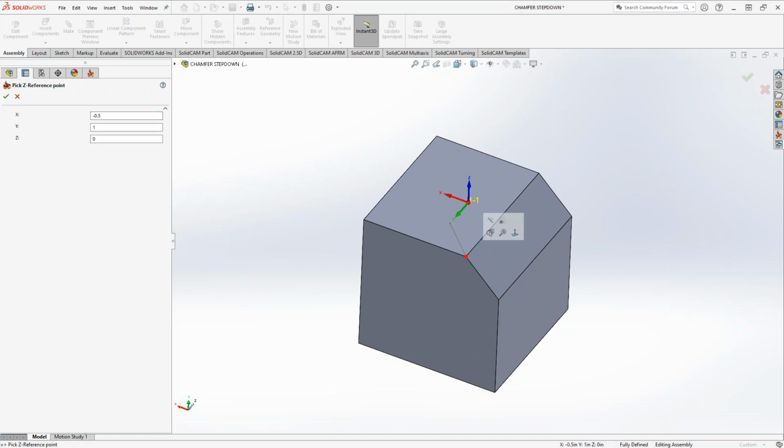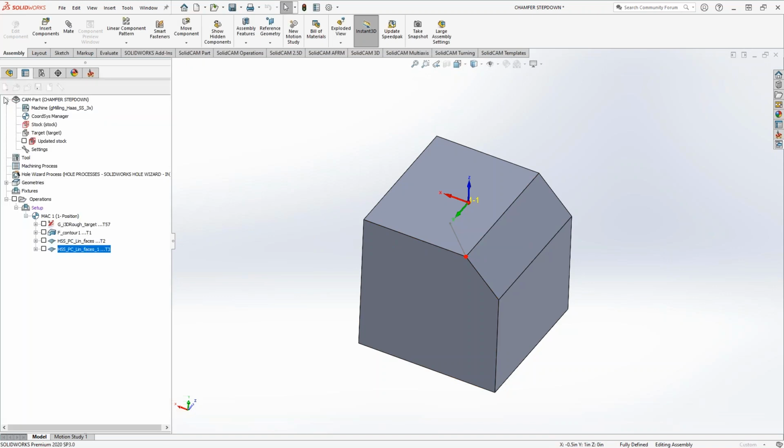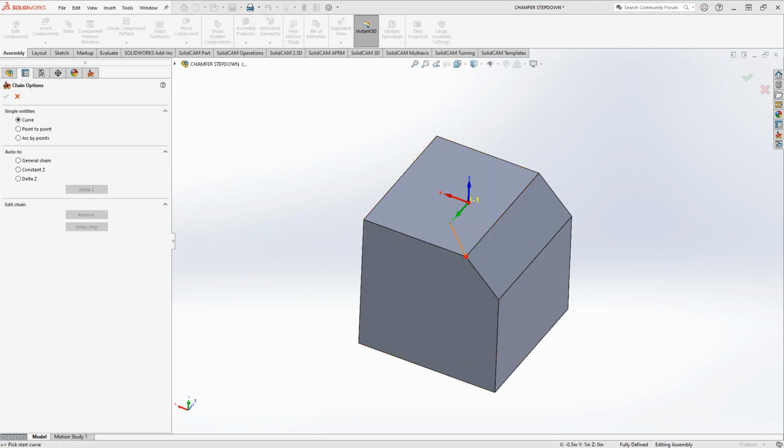And my recommendation is usually to have the reference point as that end of that chain, but also have that coincide with where you want it to fall on the path. You can probably do some sort of offsets and that sort of thing, get some sort of step down. But again, this toolpath is hard enough as it is. Just line those up in the same point, and then you'll conceptually be able to figure out what you're doing. So I'll grab that point there. And then the chain, I'll just click add, and I'll just grab the chain going in that direction.